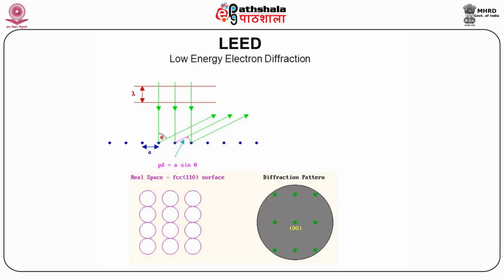The growth of NiO layers on nickel. The LEED patterns of oxidized nickel surfaces, however, mostly indicate the presence of a rather imperfect NiO film on top of nickel, which might result from the large lattice mismatch of nearly 20% between nickel and nickel oxide. Although the use of highly oriented nickel as substrate leads to considerable improvement of the LEED pattern from the oxidized surface, the large lattice mismatch always remains a problem, with the possible consequence of defect structures in the oxide film.